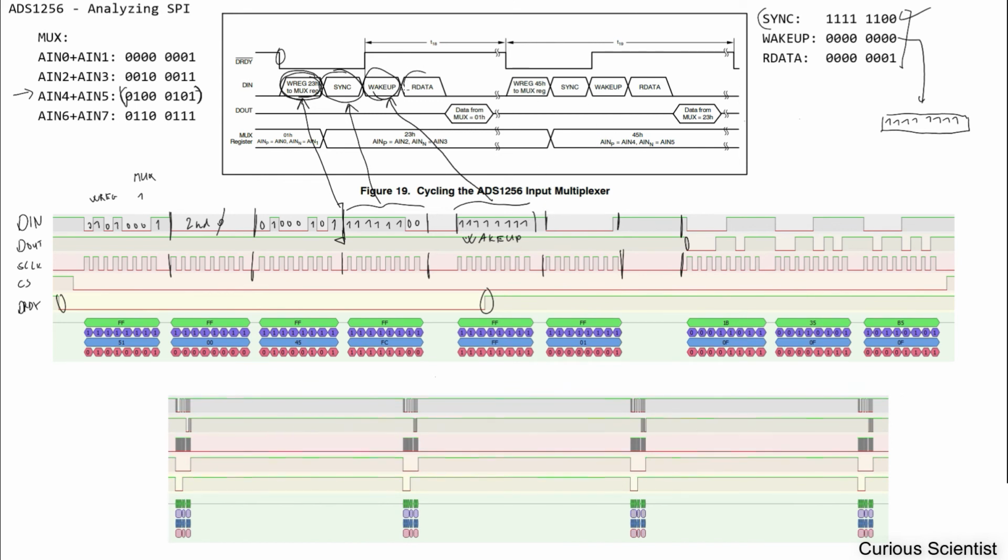Now we have to send the RDATA command, and we can see that we have 00000001, so we are fine. The RDATA is also here, and we should receive our data immediately, or as soon as the data is ready for reading out. So actually now we have to read the second line here, and these are again just dummy bytes all across this part.